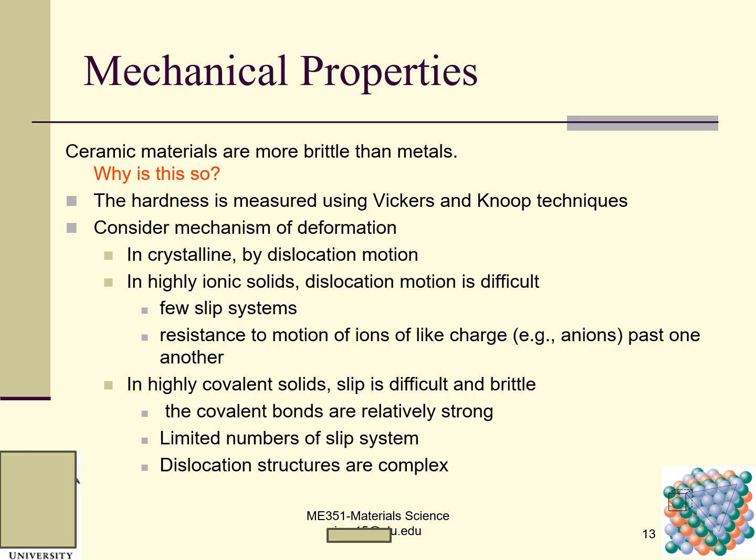Okay? But for brittle materials, for example ceramics, if we use such a huge indenter to compress the sample in order to get the hardness, we might induce cracks, which is bad. Questions? No question?